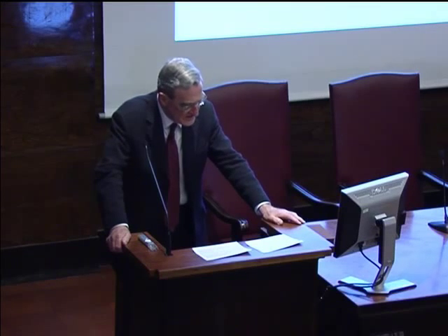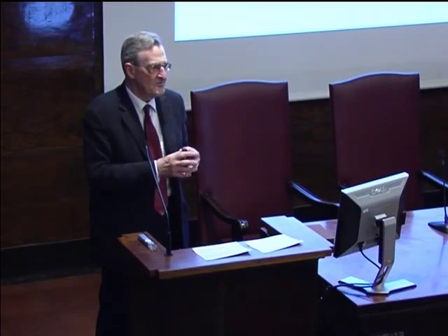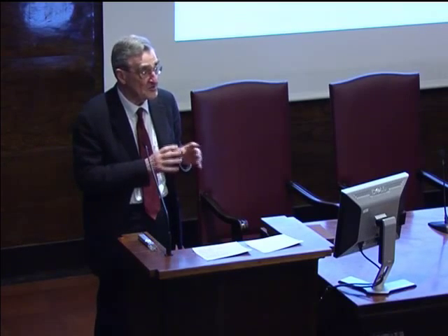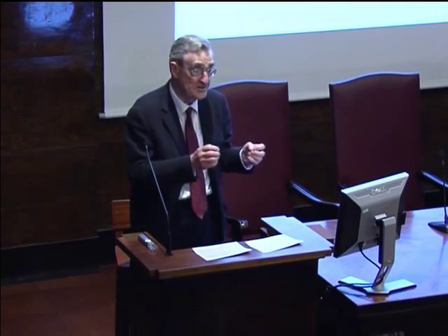And this is in severe contrast to the way a structural engineer usually thinks about a structure. In general, if you write the equations of equilibrium for a structure, a frame, shall we say, or a reinforced concrete building, one finds that these are not enough in order to determine the state of the structure. You have to make some other statements. The other statements that are made are, in general, some statement about the material properties, the elasticity, shall we say, how much the material stretches when it's stressed.